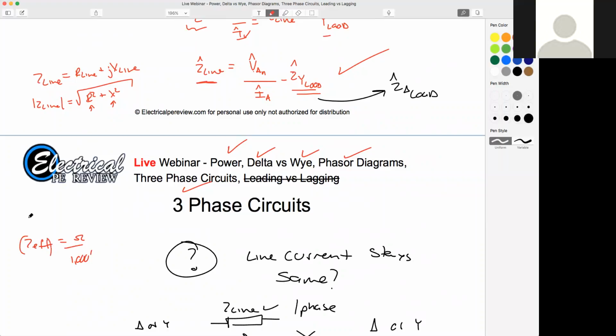So typically if we don't have a Z effective, right, they might say find 8 AWG of like copper. They'll give you the characteristics, right? The power factor. You have to look up the effective impedance, and you have to multiply that by your length to get just the ohms. If they give you just the ohms, like what we were working with tonight, then they're not going to give you the characteristics of the wire. And if they do give you the characteristics of the wire, then it would be a red herring. Omar, does that answer your question?